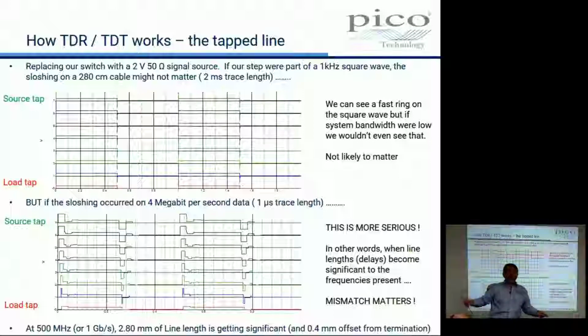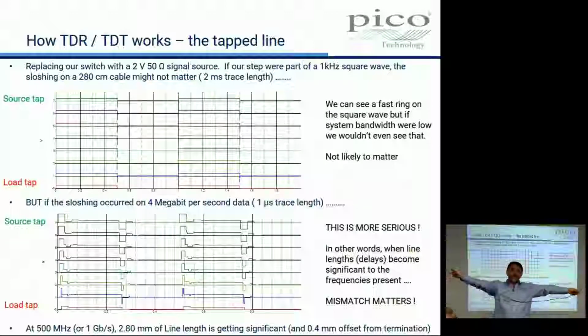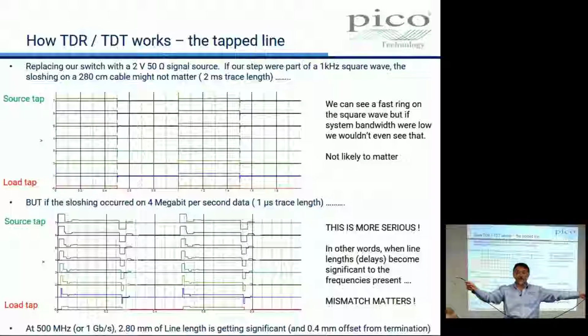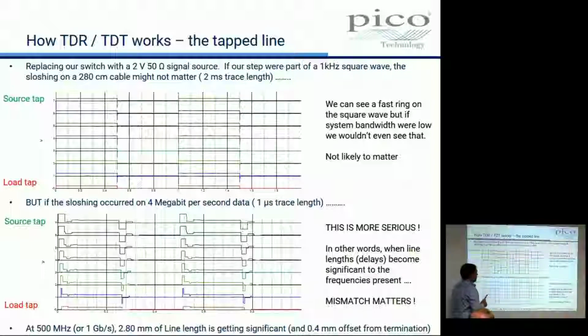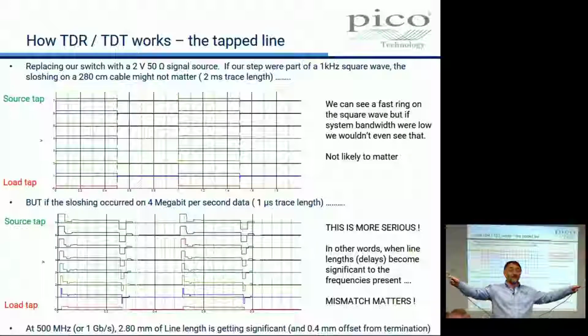Now the fact is that things with kilohertz waveforms in probably don't have the bandwidth to see those or care about those spikes. So those spikes don't hurt anything when we're doing an audio amplifier or a TV signal at megahertz or whatever. They don't really do anything. But here I've gone up to 4 megabit per second data. Now that's quite slow data actually, 4 megabit per second data. It really isn't very impressive data in a cable this long, is it?